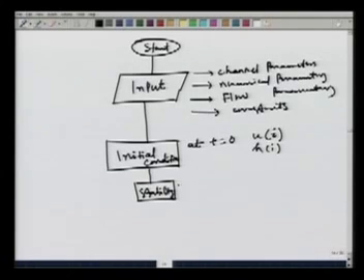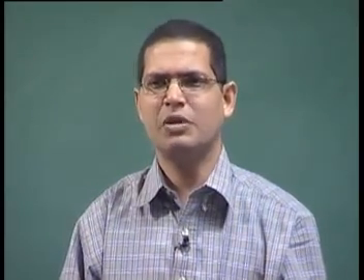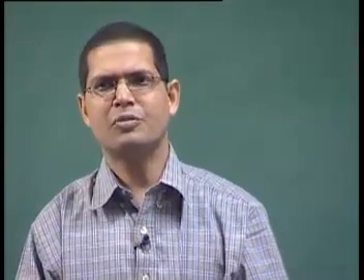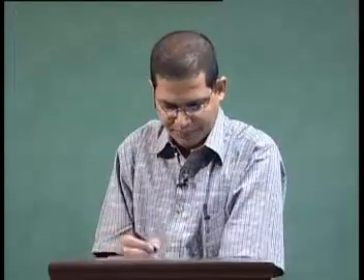For the time being, just know that stability means we find out what delta t is. Unlike implicit schemes, we have to follow certain conditions for delta t. In explicit schemes, although it looks very simple, we are paying the price here. For example, we have to follow the Courant condition to find the delta t value. We cannot use delta t values at our own sweet will.